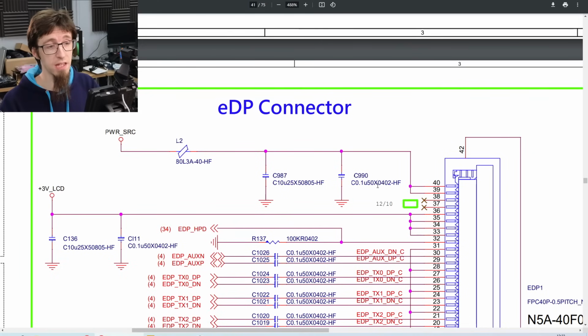The other one that was next to it is a small boy, that's an 0402, and that is a 100 nanofarad. So remember from recent videos I've done, like the MacBook repair, where I just made random guesses at the capacitor, and I said you usually see 10 microfarad with a 100 nanofarad next to it. It's not always the same, but as you can see, there's very often those two pairs, a 100 nanofarad, so 0.1 microfarads, and a 10 microfarad capacitor acting as filtering on a big power rail. So we're going to need a 10 mic capacitor, and we're going to need a filter.